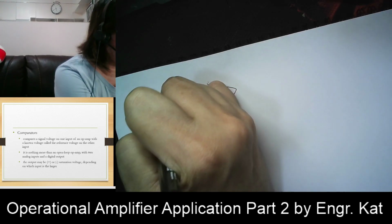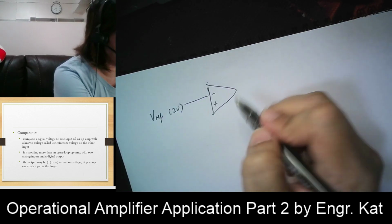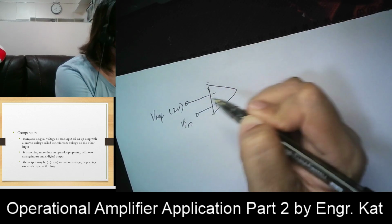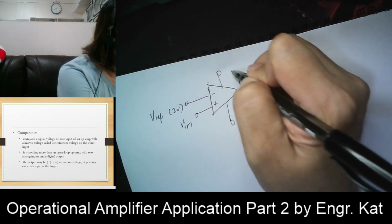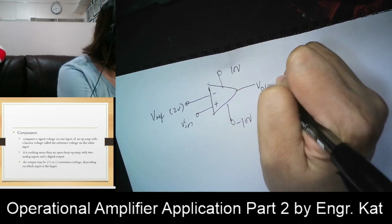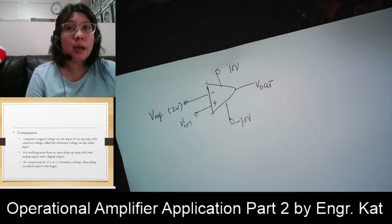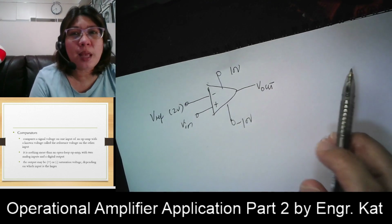Let us say we have a reference voltage which is equivalent to 2 volts, and then we place your input here. So this is your input voltage. We have here, for example, positive 10 volts, and negative 10 volts, and here your output voltage. You can have an input which is analog or changing, and at the output, you just have two values.